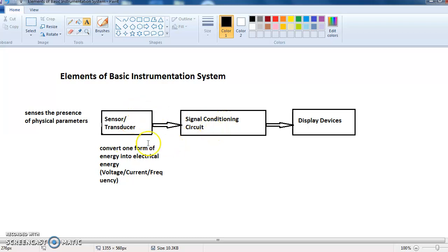Now after I have sensed some parameter, I'll get an output maybe in electrical or non-electrical format. Now if I have this kind of format, it will not be universal everywhere, right? Even if I have electrical format and if I am getting voltage, let us say from minus 1 to 2 volts, is it enough, or is it in the form of standard?